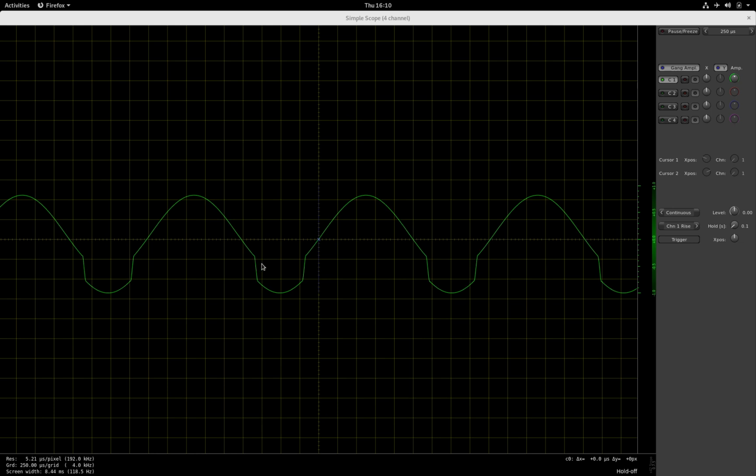However, this is not the case when the input amplitude to the fuzz is reduced. Say, if you pluck a string on a guitar, the oscillation will be a damped oscillation, so it will decay in time exponentially. Then there will be a point where the amplitude of the input signal will drop below this nonlinear region in the transfer function of the fuzz, and then the output of the fuzz would suddenly clean up. It would no longer distort. However, this is not what actually happens.